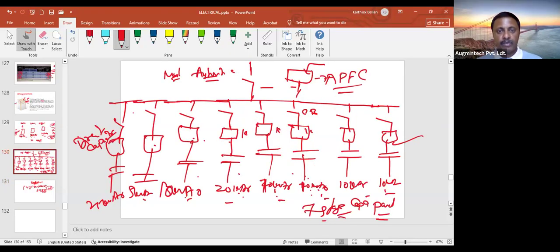Whatever it is, if your motor starts together at a time, it is also not an issue. Maybe you can provide another 5 to 10 extra kVAR to adjust it. Like 8 stage, 9 stage capacitor, that's not going to be a problem. Okay, so now let's have a look into this calculation.